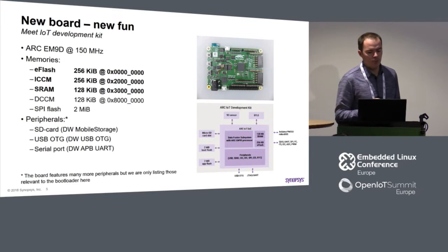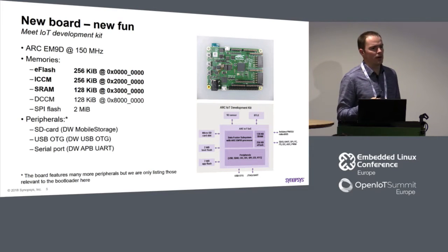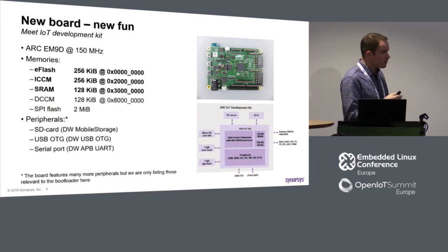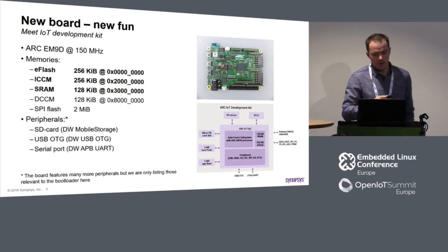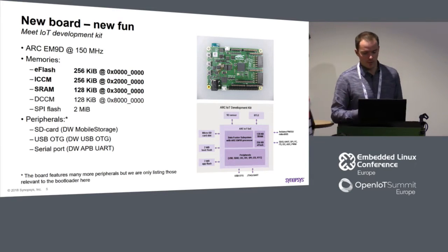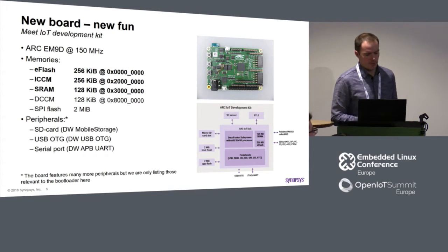And the idea to use a bootloader was to allow users to run their own applications without additional debugging tools. You don't need to use JTAG whatsoever. You just build your application, put it on an SD card or on USB storage, and plug that into the board. You may see that there is a USB OTG connector and there is an SD card slot, but probably you don't see it on the other side. And you may just run it without additional tools, which at least for me looks quite nice because you don't need anything extra.